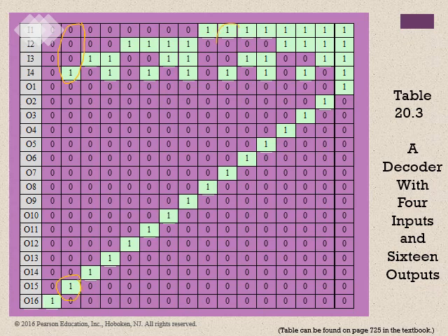If it's 1001, it will perform output 7. This is a simple one, for a 4-bit binary input. Of course, a typical control unit will have a more complex decoder to account for variable length opcodes.